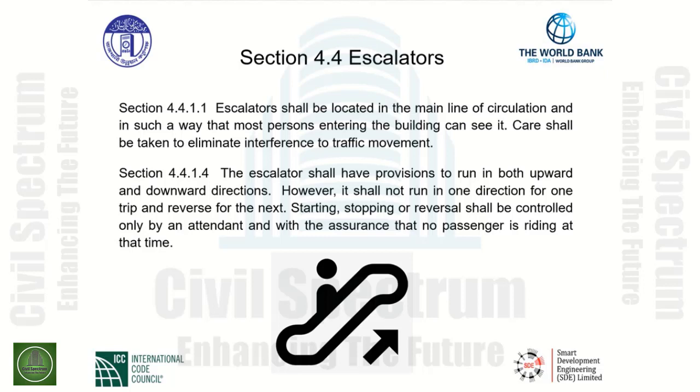Now, the next section is a directional requirement. Section 4.4.1.4 gives us the requirement that the escalator shall have provisions to run in both upward and downward directions. However, it shall not run in one direction for one trip and reverse for the next.